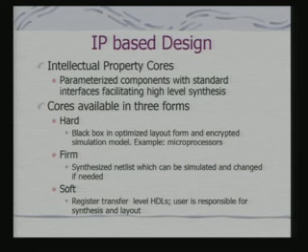The interface of that reusable component has to be known, and known to whom? Known to an application developer who is designing the system on chip. Now, these cores are available in a variety of forms for this purpose. We call them hard core, firm core or soft core.